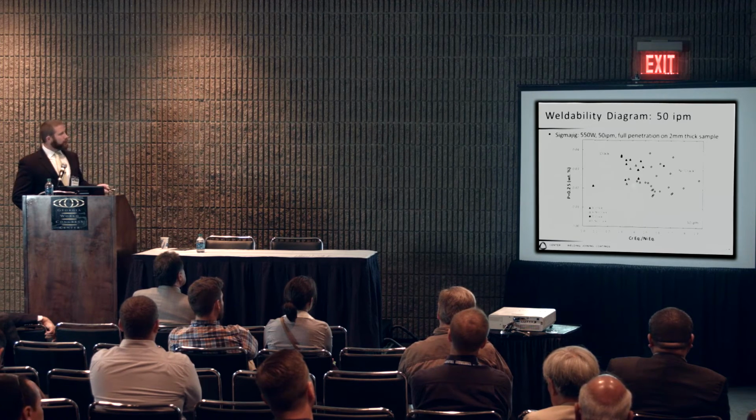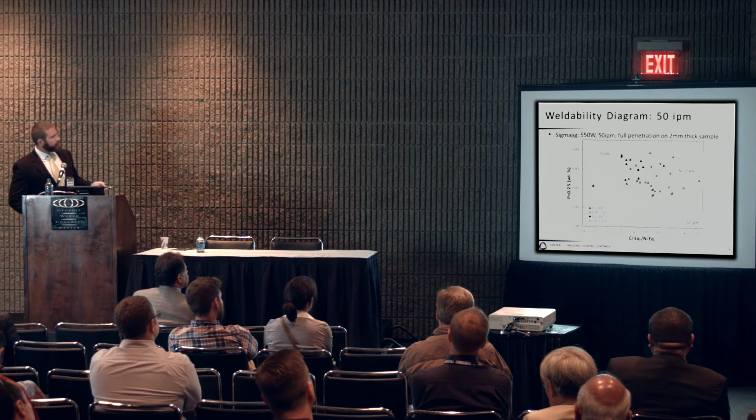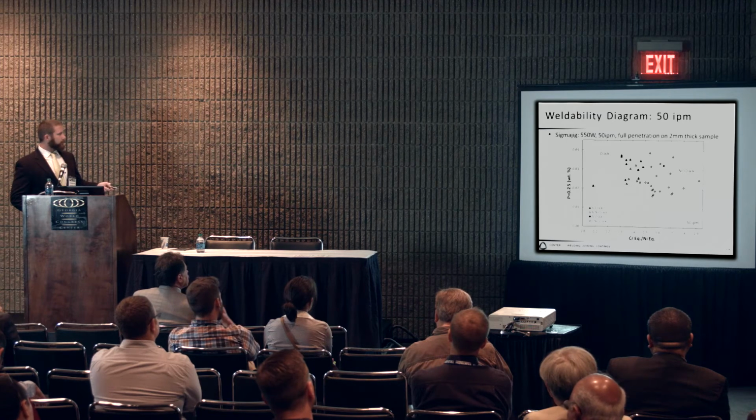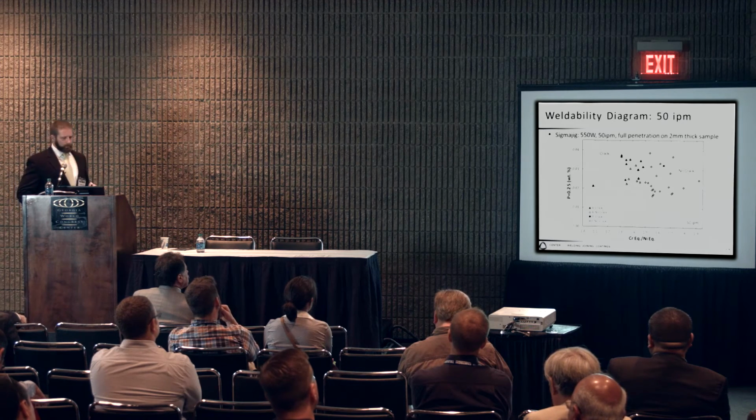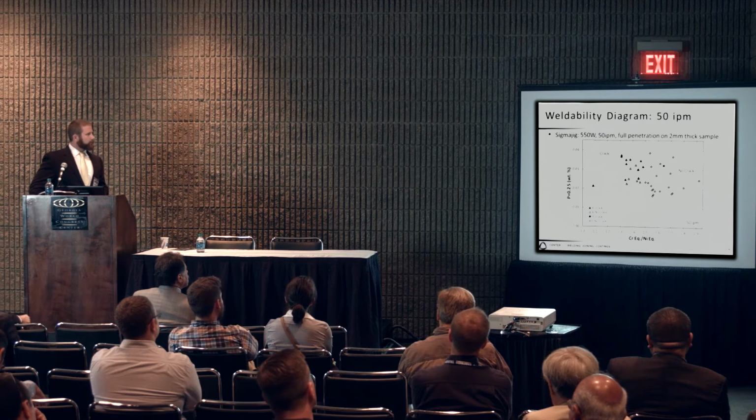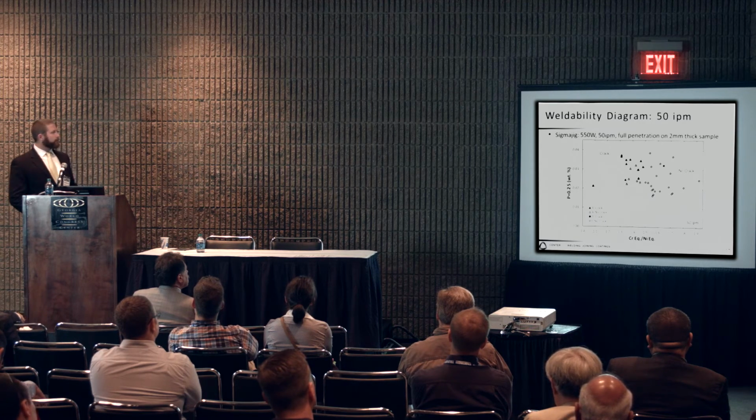And then a little bit of slope to our vertical crack, no crack line, because we do observe some alloys with similar chrome over nickel equivalents, but we have primary ferrite here, but primary austenite at higher impurity contents. So don't know if impurity content could be influencing solidification mode slightly as well.